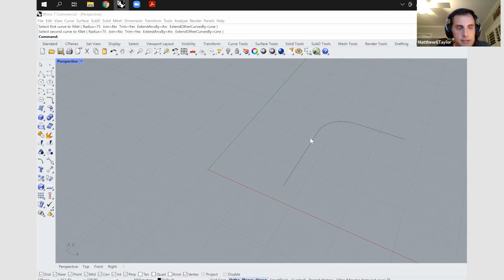He says, okay, trying again, couldn't get that to work. The main reason a fillet would not work is that when you fillet, you need a radius. If you imagine something being 100 millimeters by 100 millimeters, and you come in with a fillet that's 10 meters, it's just going to say, will not fillet. If you come in with a fillet that's too small, it would work, but you wouldn't be able to see it. It would still just look like a corner. So try around with some radiuses to know what scale you're working in. I would imagine that's probably the issue, but do let me know.